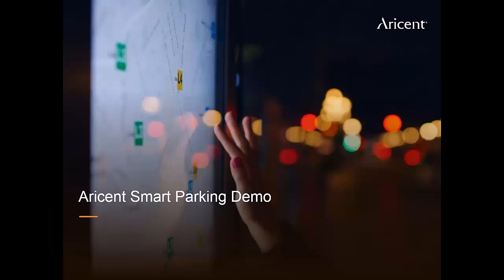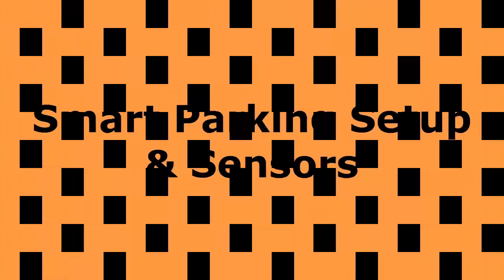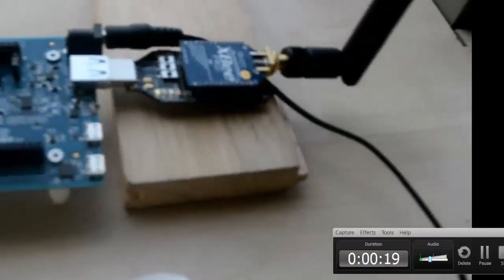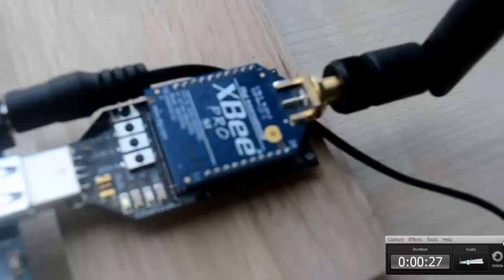Welcome to the smart parking demo. We will start with the setup details. The setup is running in the Aricent corporate office in Gurgaon. It consists of 3 Libelium parking sensors inserted into the hole and covered with epoxy resin. The gateway is based on the Intel Edison and has a Libelium XBee receiver module that receives the sensor signals over an 802.15.4 radio mesh network.